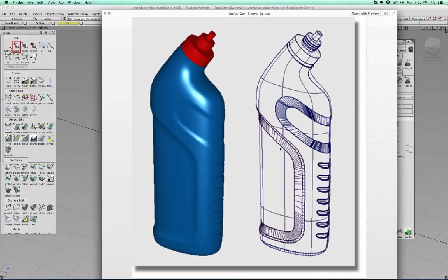So let's take a look at what would be a very efficient approach to build this vessel. If you break this one down into geometrical problems or objects, you see this is symmetrical, that's a cylinder. Most of the lower body is symmetrical, so it's also another cylinder. Just the part in between deforms, so it looks like a blend. And it also makes a transition from something more flat to perfectly circular. So this actually tells me already how I could approach building this one.